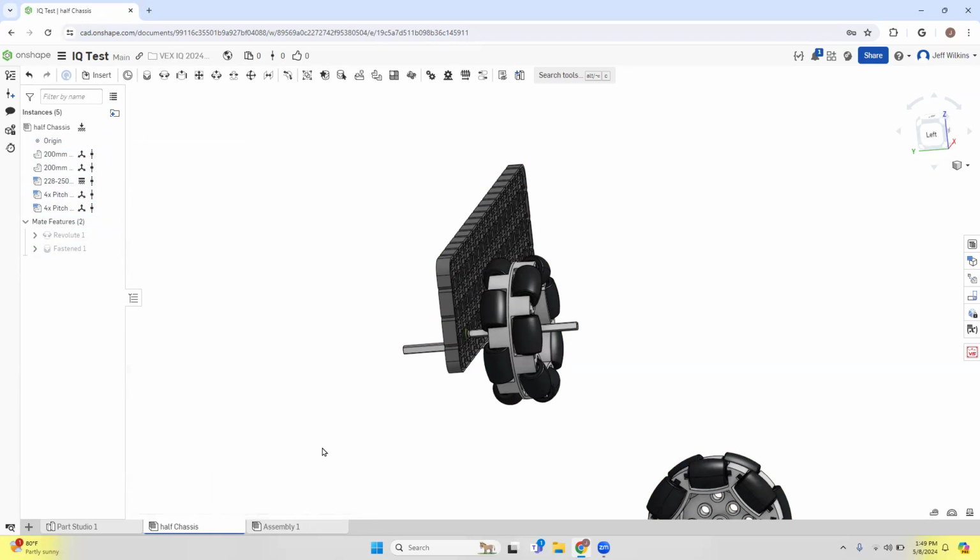And you can do this for an arm. You can have the forearm, you can have the claw, and then those go into a sub-assembly that's called the arm. And then that arm sub-assembly goes into your full robot assembly. So you could do things like that when you build. That way, if you have to make modifications to things, you're not hunting around for all these things.